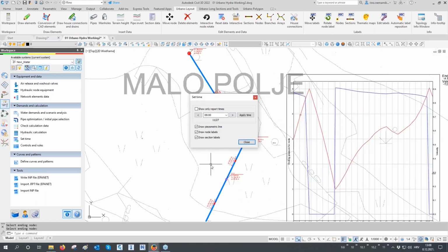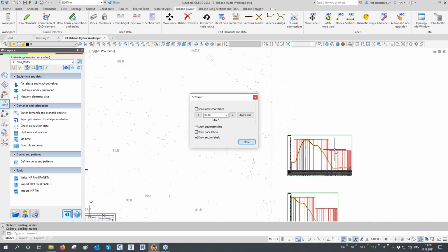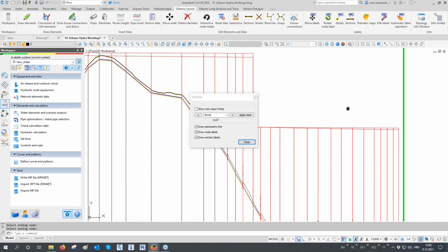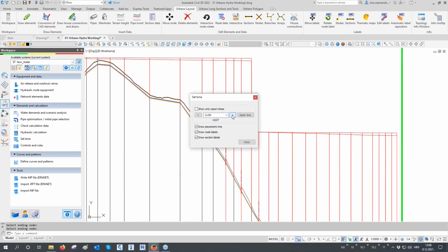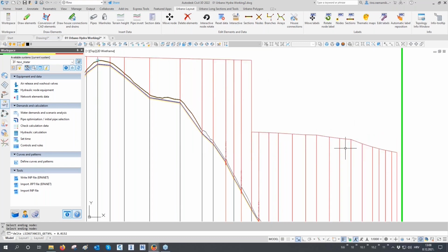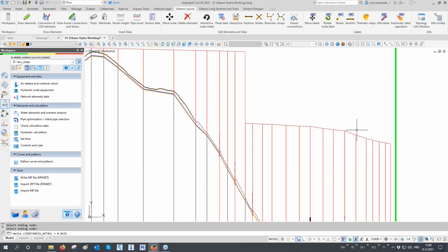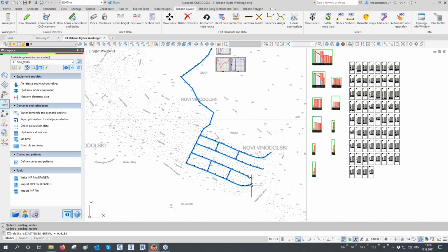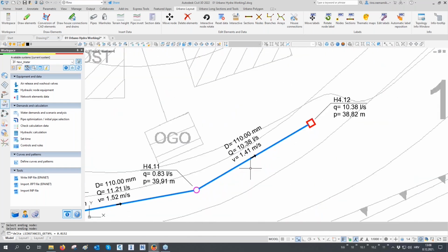And now when we come to this point, so 7:12, the pump is again turned on and you have the flows. And also if we go to our profile, we can check the dynamic piezometric lines. So check how they are dynamic, they are moving. And for example, when you come to some part of the day that you would like to save and apply, you can apply it. And now these results are applied. So here you have the permanent piezometric lines, you have the permanent label are now applied, and they are now showing our peak flow.